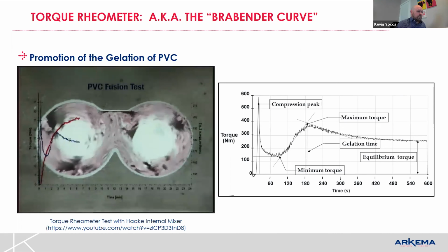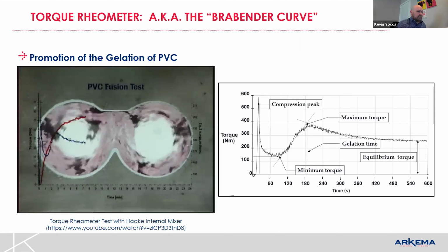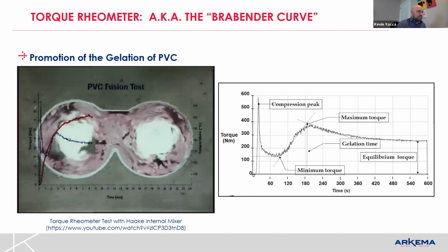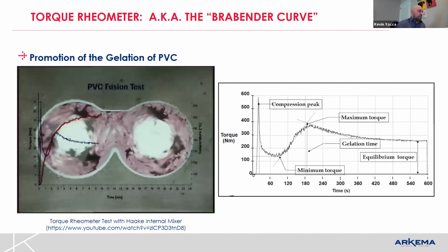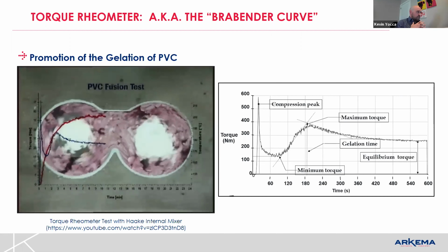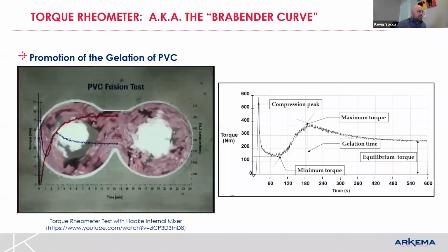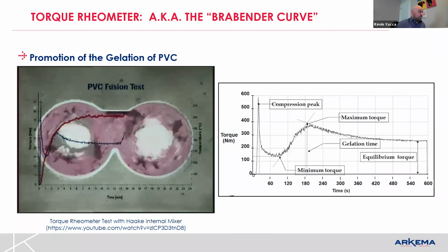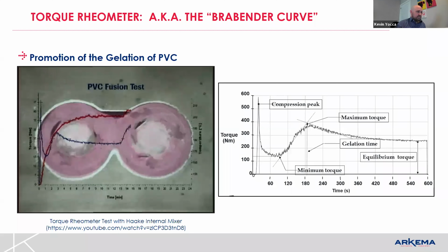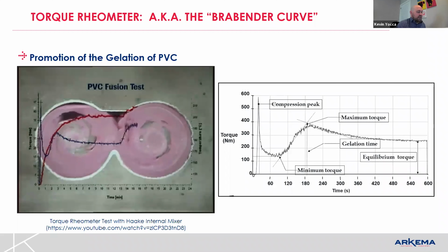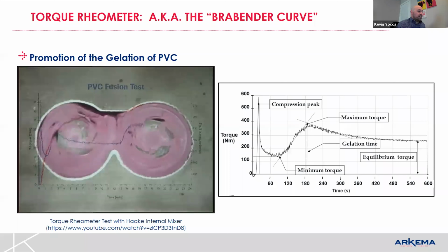And then as we go through the powder actually interacting and becoming fused, we're working through the gelation process at this point. We're starting to build that 3D network because we're getting more entanglements of the primary PVC particles. And basically through the processing time here, which we're mimicking for an extrusion process, we're trying to see, okay, how high of a torque do we get?